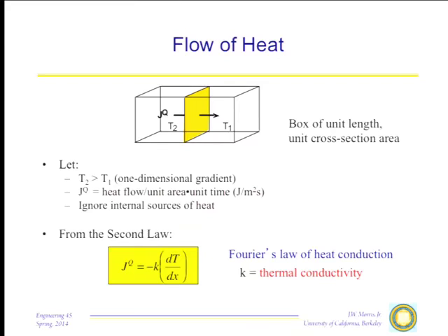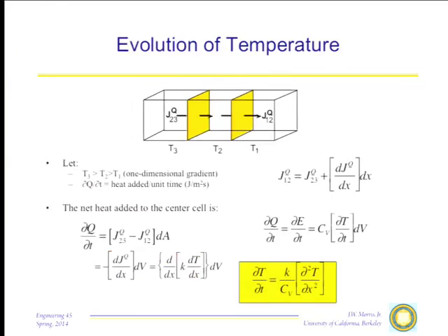The lead term in that Taylor expansion will look like this, because when the temperature gradient goes away, the heat flow goes away. Well, that's a digression of sorts, because in most books you see this stated as a law of physics. But most of the so-called laws of physics are Taylor expansions. What must happen is there must be a heat flow. The lead term in the expansion for the heat flow is this, and that's called Fourier's law of heat conduction. The material property here is the thermal conductivity K. So that's the thing we've got to understand: how heat is conducted in materials.